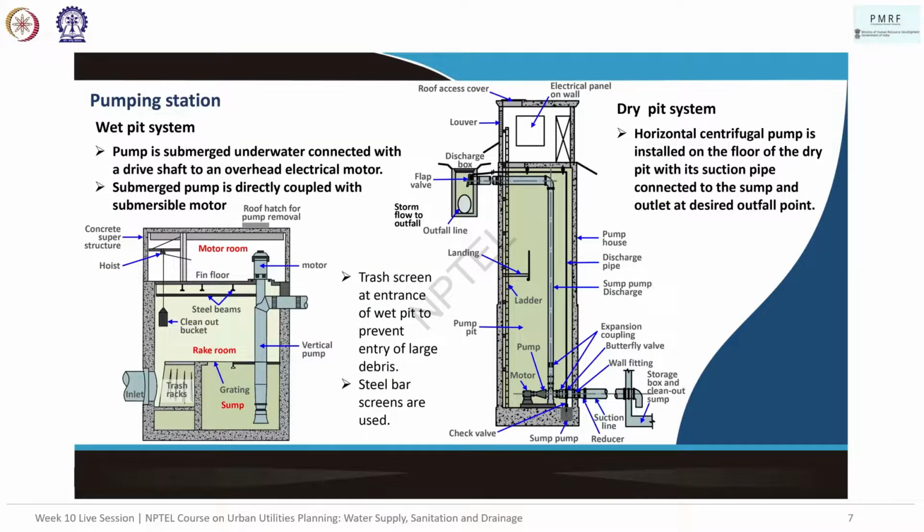So with regard to pumping stations, I know the question was probably mildly ambiguous, because dry pit and wet pit could also refer to the soak pits that we usually have. However, if we look at the answers, we see that it's actually regarding dry pit pumping stations. Basically, the pump doesn't come in direct contact with, or isn't immersed in, the sewage as such.